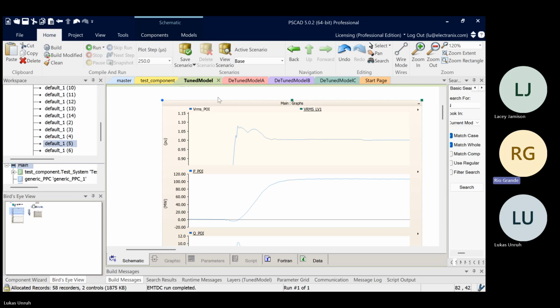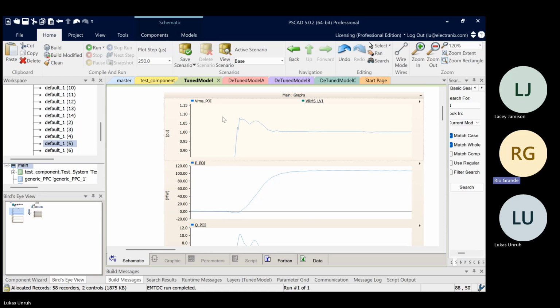While it's resyncing, you might see current that is maybe not what the grid needs. So active power might go negative briefly. Reactive power might go sharply positive as that angle is perhaps not aligned with the system angle yet.